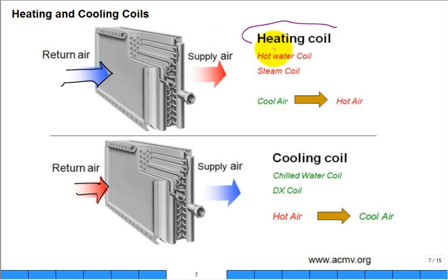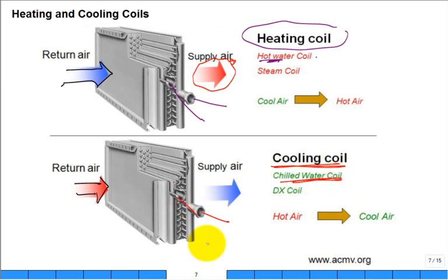So if you have what they call a heating coil, maybe you put hot water through that heating coil in the tubes, in and out of the tubes, and then the air goes across, and they even color-coded it. Look at that. It's red. That's a little warmer. But they color-coded down here. In the summer, you may have chilled water, cold water going in and out of the tubes. That's what we have on campus. In our mechanical rooms, we'll have a heating coil, and then close to it, somewhere else, will be a cooling coil. And it'll supply cold air to the interior of the building and rooms.